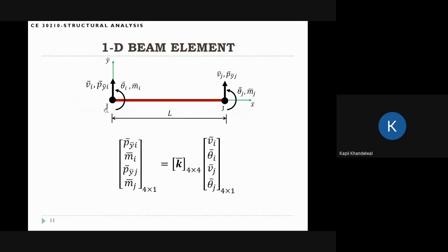Okay, so for the beam element, we will always say the left-hand node is i and the right-hand node is j, and the degrees of freedom are always ordered as vi, theta i, vj, theta j. This is extremely important because that's how we build the stiffness matrix here. Again, the bar indicates the local axis, but we'll not emphasize the bar because a beam is always in the local axis. But this is important.